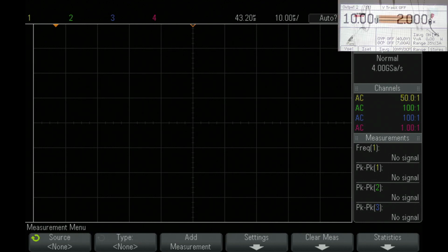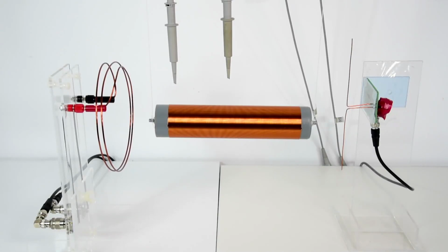I switch over. Here in front of you, you see the setup arrangement. A 2-turn coil of 2 mm copper wire is the exciter coil, on the left, followed by the DUT in the middle, which is hovering over ground via nylon wires attached to the ceiling, and the dipole antenna as the main probe of the frequency measurement on the right side. On top of the coil are 2 oscilloscope probes to show the overall wave characteristic of the unterminated floating coil.